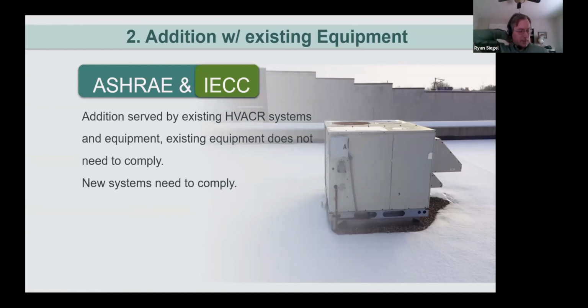existing equipment, understanding that most HVAC systems do have some excess capacity that can be used to serve an addition, and we have touched on this in the past, as perhaps identifying extra capacity through the use of runtime, which can be available either through data streams or perhaps a building automation system or smart thermostats. Alternatively, you might also look to the ASHRAE standard 183 as far as trying to identify